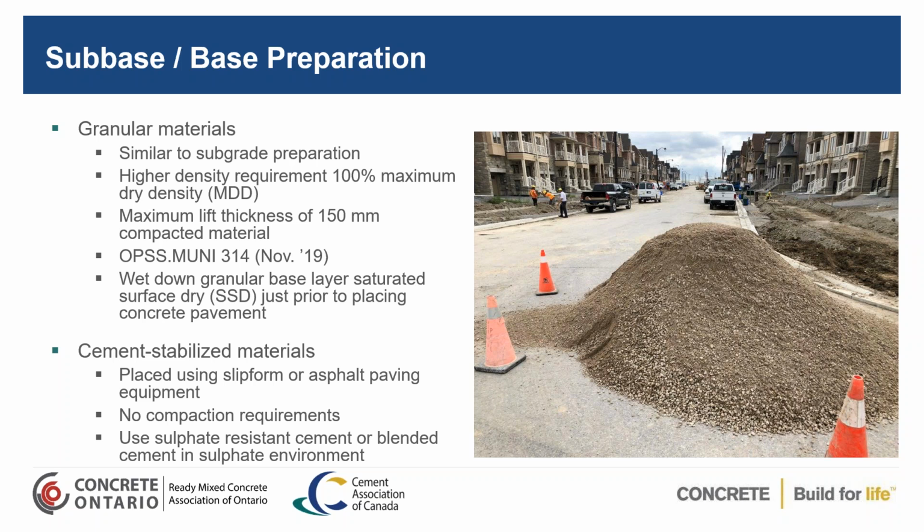underneath your pavement. And with concrete pavement, the key thing that you're looking for is uniformity of your base material and your subgrade. So you want to ensure that you put these thinner layers and compact them appropriately as identified in OPSS Muni 314. Now, another key thing to do just before you start paving, you want to actually place water on the surface of the aggregates if they're dry, because you want them saturated surface dry so that you won't take the moisture out of the bottom of the concrete, which may actually not get complete hydration of the cement at the bottom of the concrete, and you'll end up with a weaker concrete than you designed for. So that's a key thing to do when you're looking at the pavement.